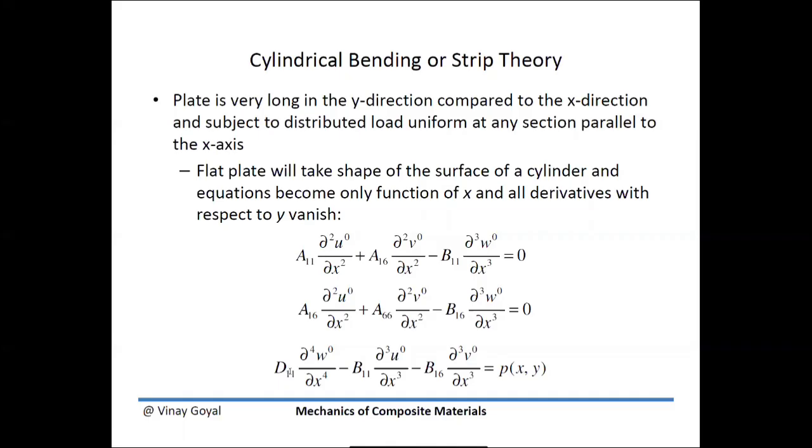Okay, and in fact, we can prove, and you should be able to demonstrate this, that D11 is basically 1/12 B H cubed times E. So you basically get the same EI type term that you would have gotten through the equations from mechanics of materials for a beam under distributed loading. Here you have additional terms, and it's quite understandable because we have a more general formulation.